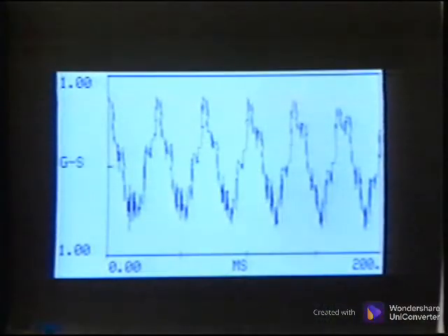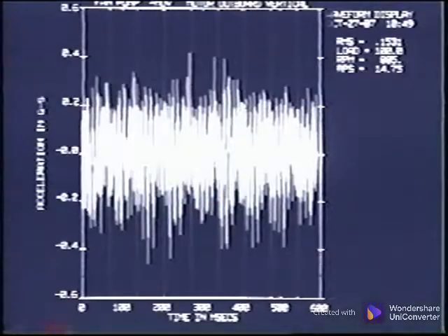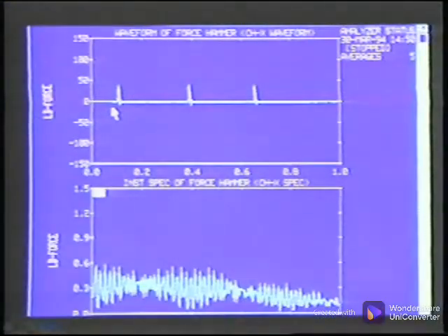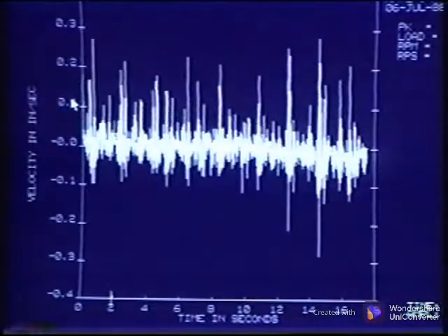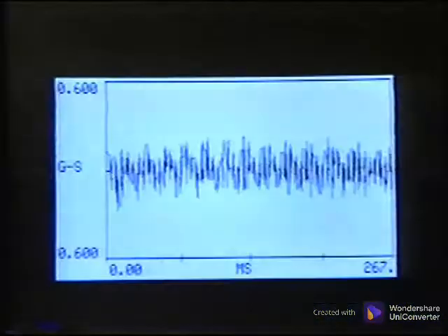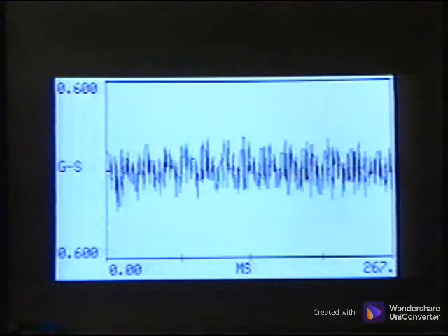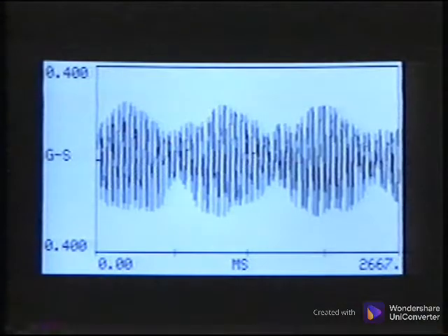With adequate waveform resolution, you will be able to pick out certain patterns in the waveform to determine whether the energy is periodic with repetitive energy, complex and varying, impacting with random or repeating spikes, or has discontinuities, or is asymmetrical and has truncation, whether there is influence from process or electrical frequencies, whether there are low-frequency events or modulation. Let's consider each of these waveform characteristics in detail and the effect it produces in the spectrum.